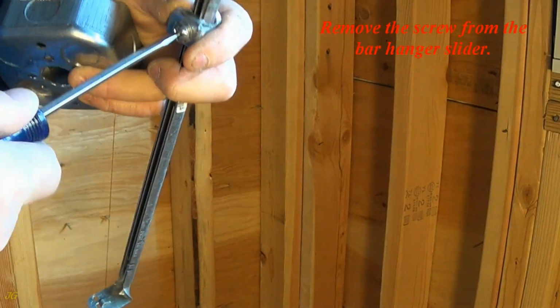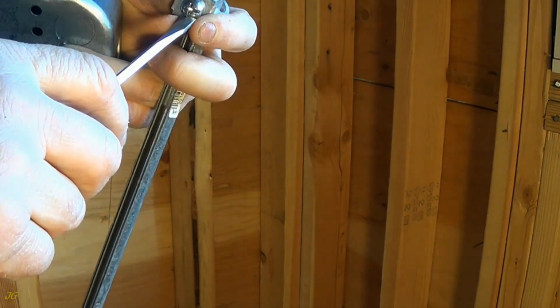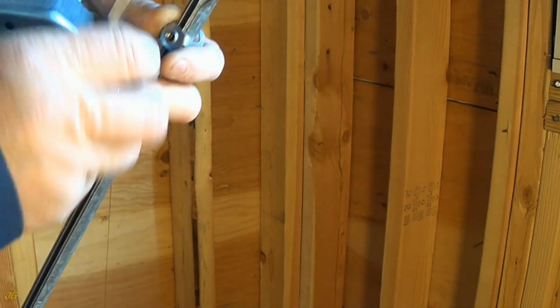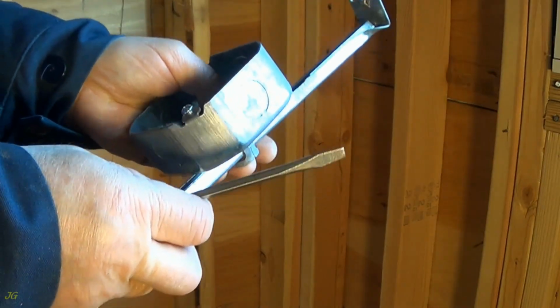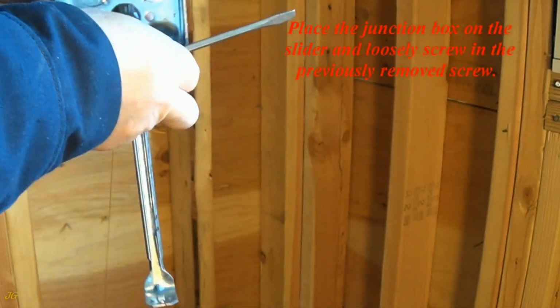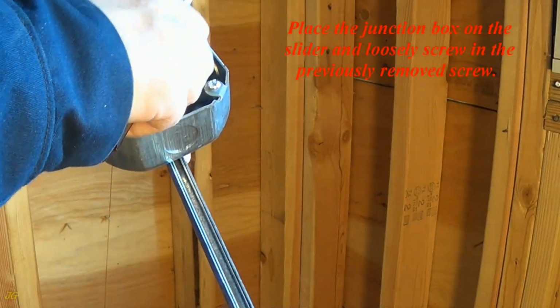Remove the screw from the bar hanger slider. Place the junction box on the slider and loosely screw in the previously removed screw.